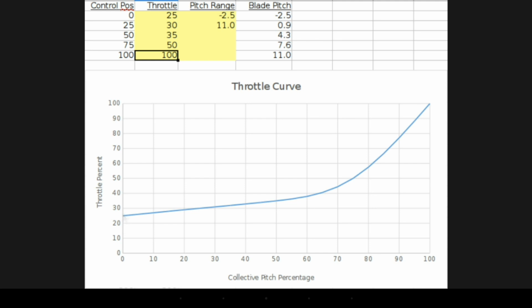So this helicopter can be idling, and when we release the throttle hold and it starts to spool up, leaving that collective stick at the bottom, this helicopter will spool up to what is called a ground idle rotors turning throttle setting, which engages the clutch and starts turning the main rotor and tail rotor, and it brings the rotor just above the speed where the clutch is engaged between the engine and the drivetrain on the helicopter.